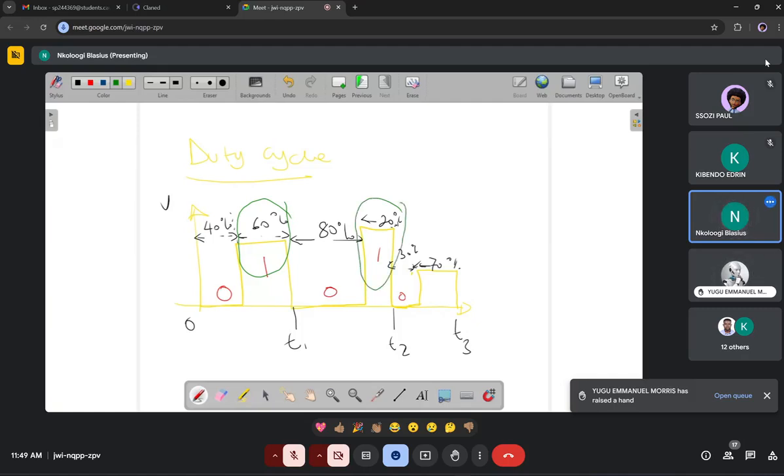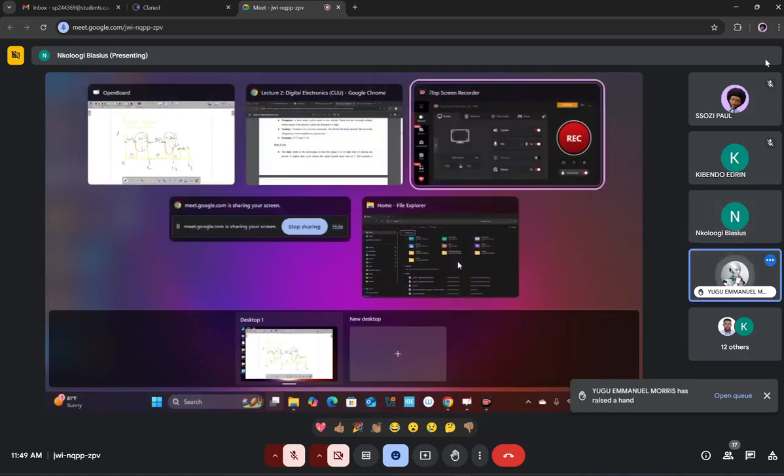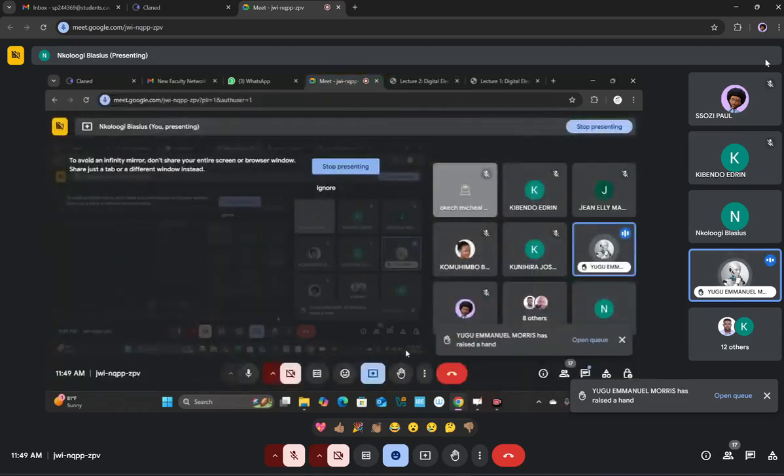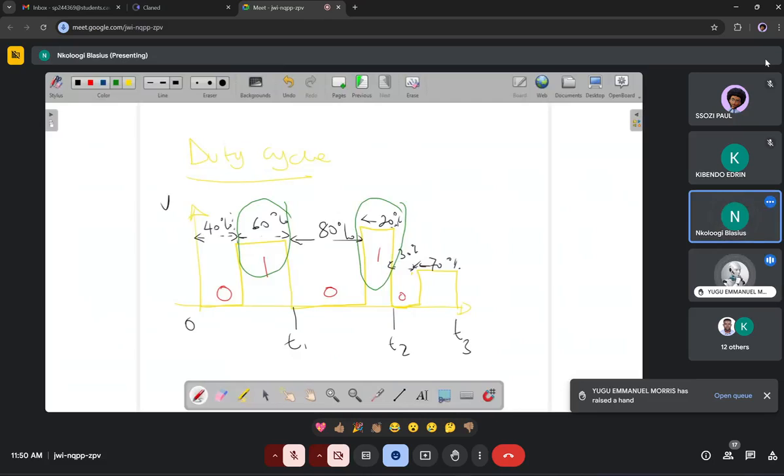Yes, please. The current is at 0, but we are still rating it as giving some percentages. Can you put that diagram back? There is where it is still 0, but we are giving percentages, 40 percent, and then 80 percent when it is still at 0. I don't understand. That is a percentage of that cycle, the percentage of that cycle to be either off or on.